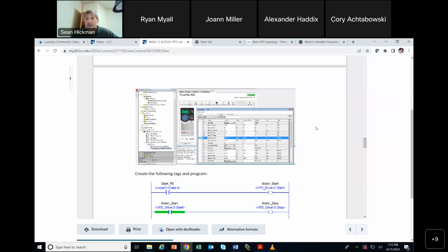The drive, you're going to set it for the nameplate of the motor, which I think is 230. Well, you set it for 230, but we have 208 available, so usually it's 0 to input voltage. If you have 208 available, typically on a drive, that's what it would be. If we had 460 available, that's what it would be.